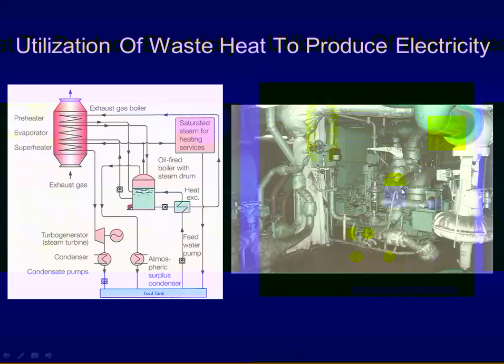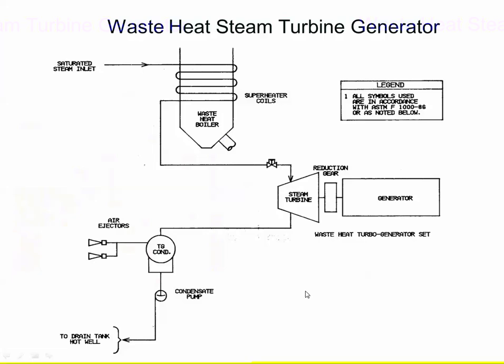All right, combined cycle. Here's the steam turbine that I use to pick up the extra heat. So with this, I still have, in this case, an economizer. So the feed pump is going to go through an economizer and into the drum. Here are my evaporators. And then I also have a steam turbine and an atmospheric condenser. So again, this is by definition combined cycle. I take my saturated steam, put it through a superheater, and then use that to drive a steam turbine.